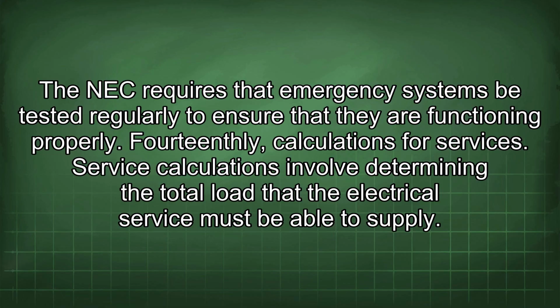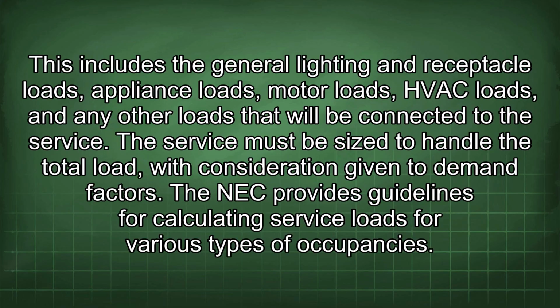14th, calculations for services. Service calculations involve determining the total load that the electrical service must be able to supply. This includes the general lighting and receptacle loads, appliance loads, motor loads, HVAC loads, and any other loads that will be connected to the service. The service must be sized to handle the total load with consideration given to demand factors. The NEC provides guidelines for calculating service loads for various types of occupancies.